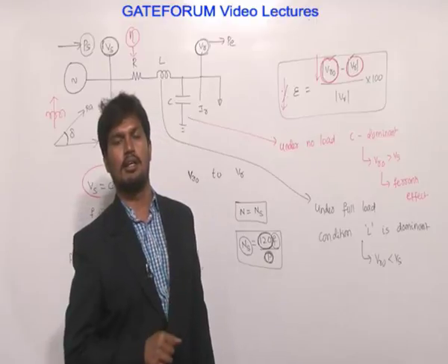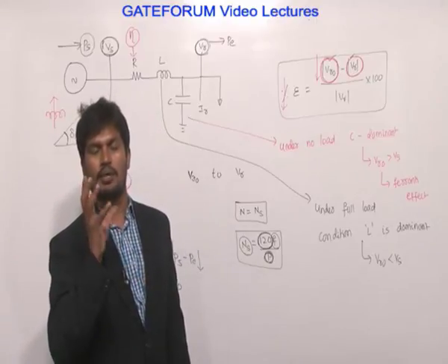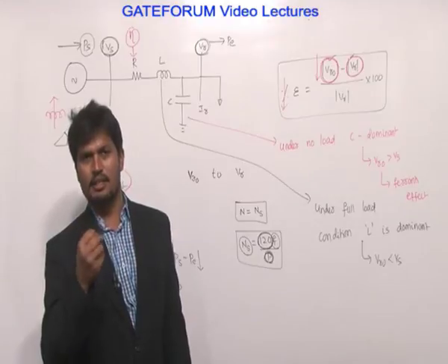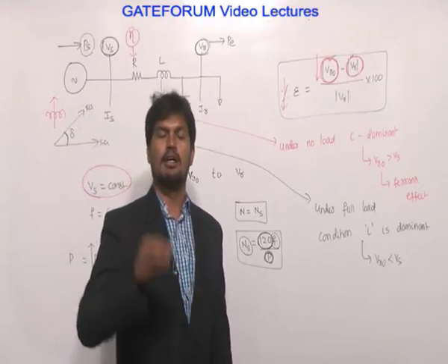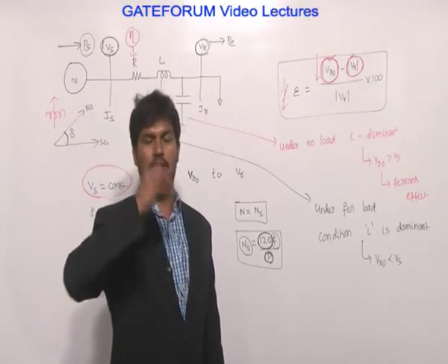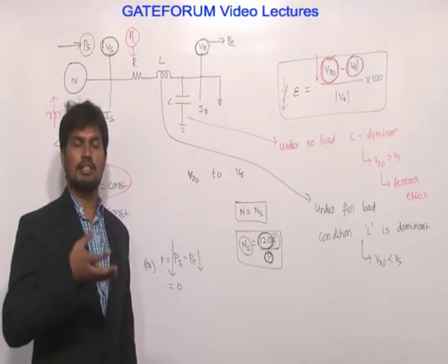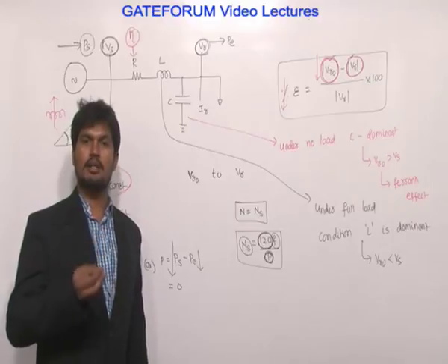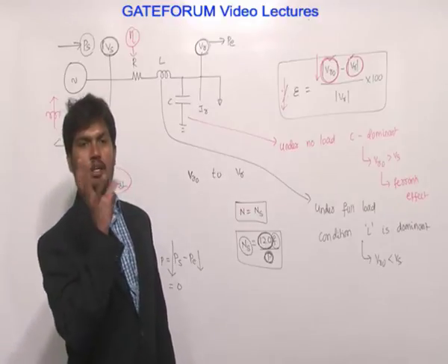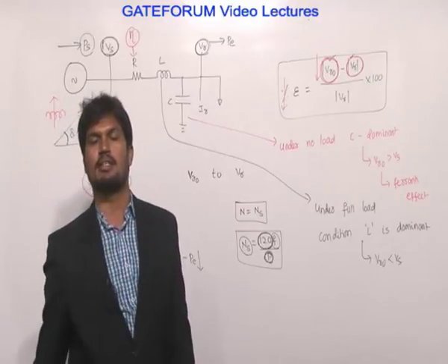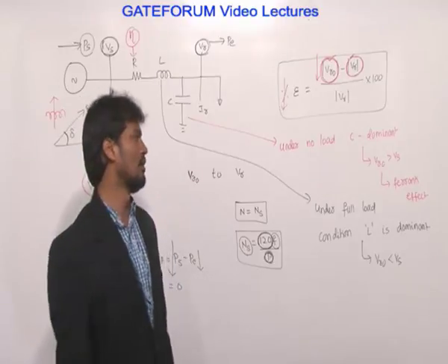Switch on the electrical fan. The inductor eats the voltage, therefore the speed of the fan is very less. Because of inductive behavior, voltage at the load point is less. In order to improve the speed of the fan, we require more voltage so that torque also increases. To provide more voltage at the fan coil, we place a capacitor above the coil. Therefore, capacitance will improve the voltage.